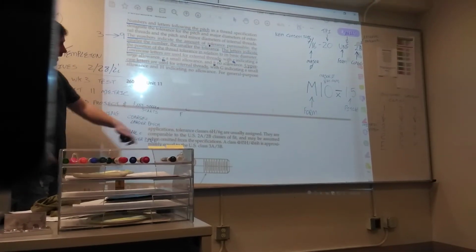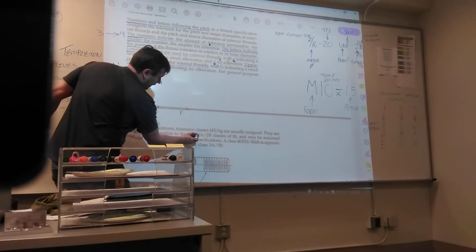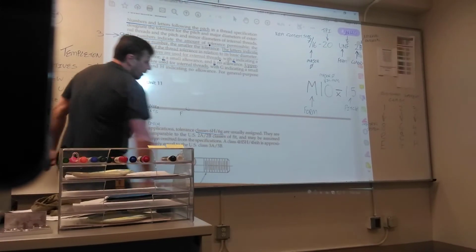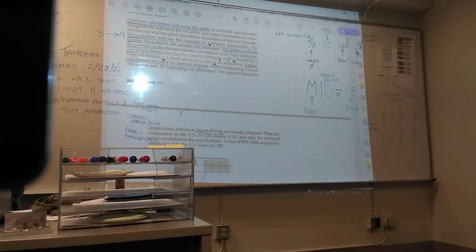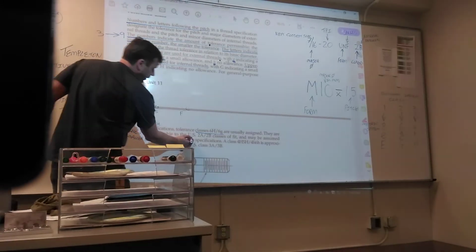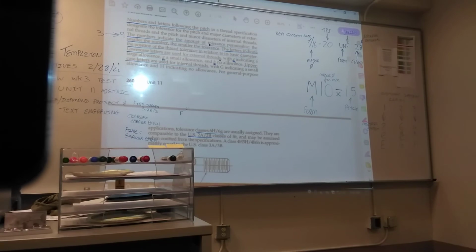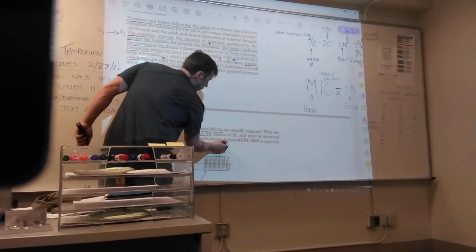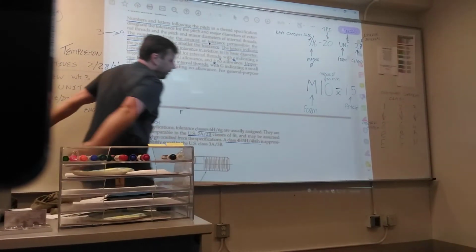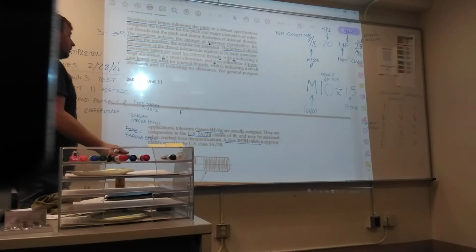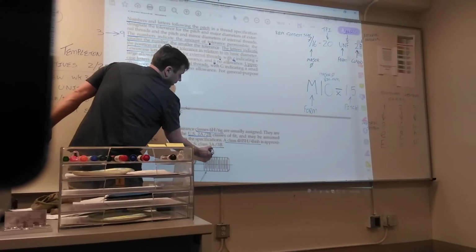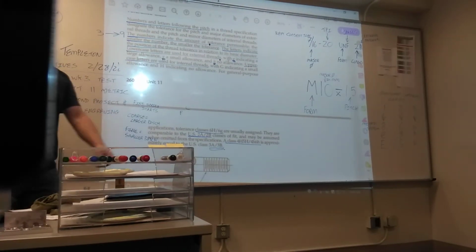So on the next page, just highlight this part. That's 6H, 6G is the equivalent, or rough equivalent, to a 2A or 2B. And the 4H, 5H or 4H, 6H is similar to class 3.